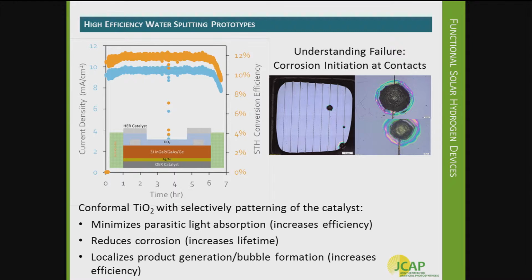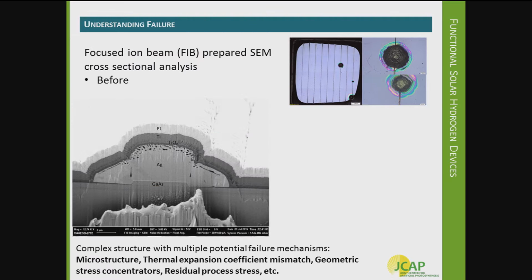If you optically inspect the device after this test, you see that there are a few discrete failure points on the surface. These actually occur at these contact catalyst stack systems that I was describing before, and because these are not self-passivating materials, there is a kind of catastrophic failure of the material. It's bulk etching, and this will propagate until the material is actually no longer present, except as corrosion product in solution.